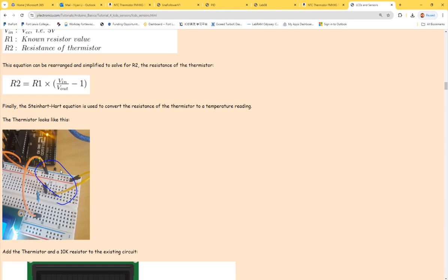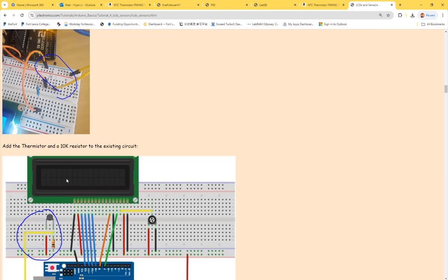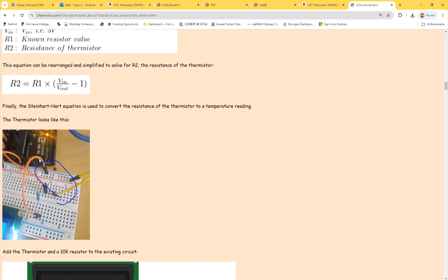See, it's just a very simple voltage divider, right? It's a thermistor and a 10K resistor that eventually goes to ground. So the 5 volts to ground is divided, and it's being digitized by the ADC inside the microcontroller. So very simple project, and with the display on it. If you want to work on this project, I highly recommend it, because I can eventually use it for the board I will teach in the class. This is one project you can use, very simple, and it's a good contribution.